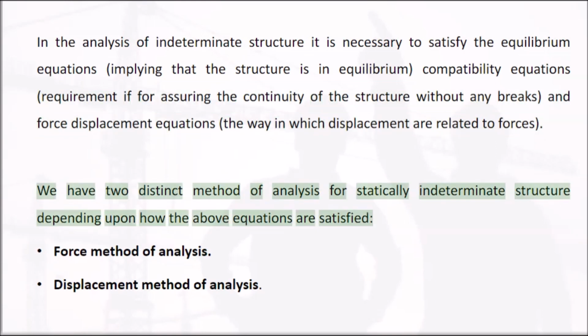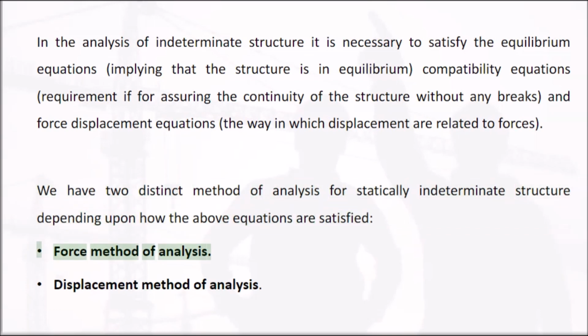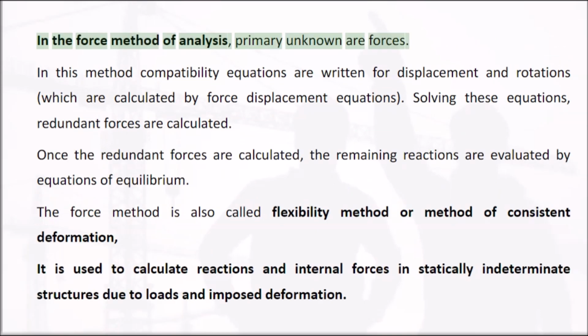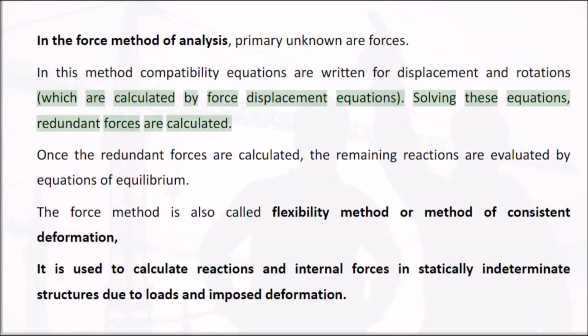We have two distinct methods of analysis for statically indeterminate structures depending upon how the above equations are satisfied: force method of analysis and displacement method of analysis. In the force method of analysis, the primary unknowns are forces. In this method, compatibility equations are written for displacements and rotations, which are calculated by force displacement equations.